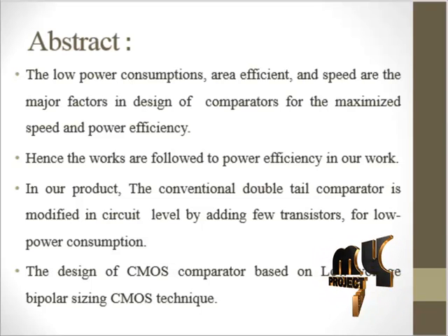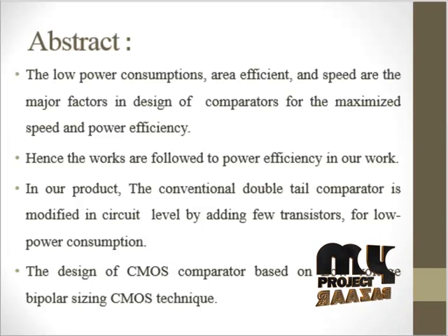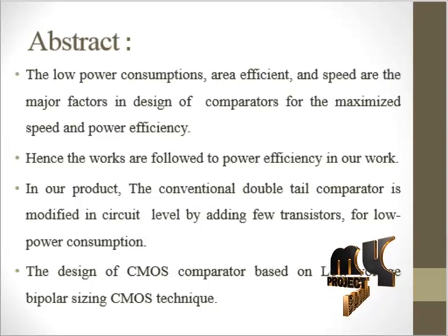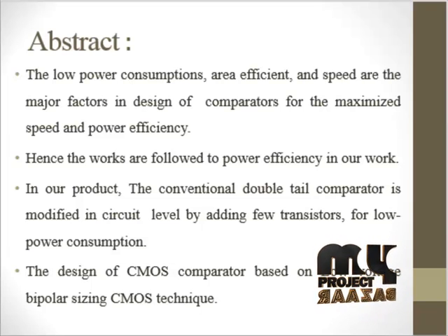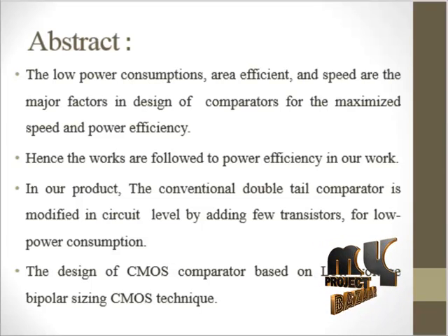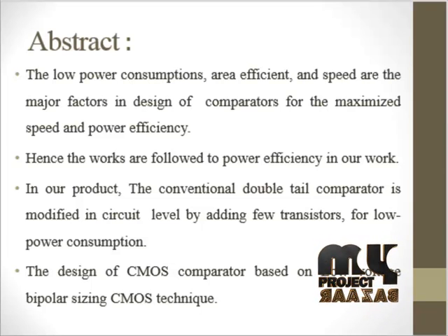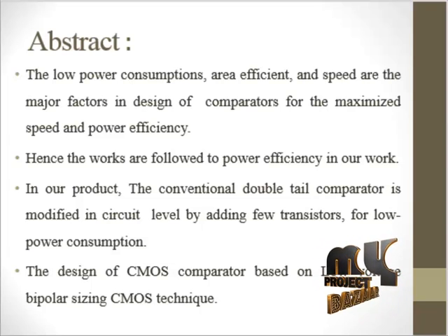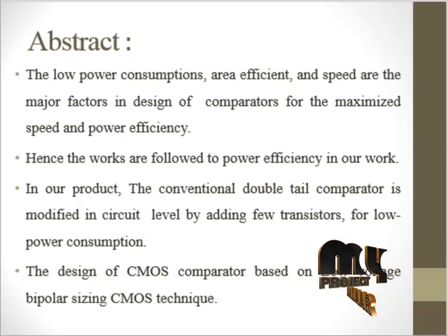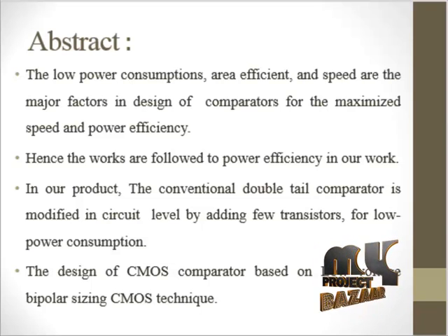When the differential voltage of the latch stage is large enough and the latch stage has made its decision, an extra gate stops the pre-amplification process. The extra gate reduces the voltage swing of the pre-amplifier output after the decision, reducing the pre-amplifier stage power consumption without affecting the comparison speed.